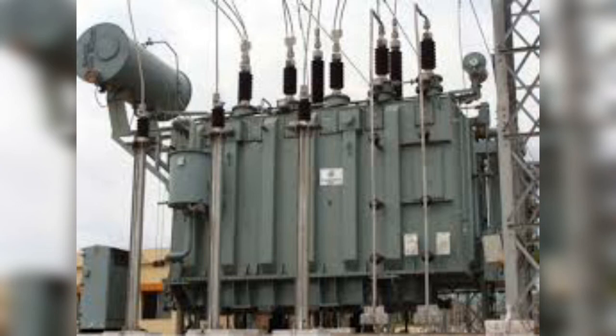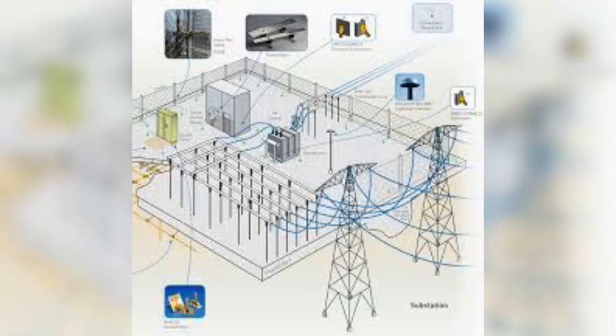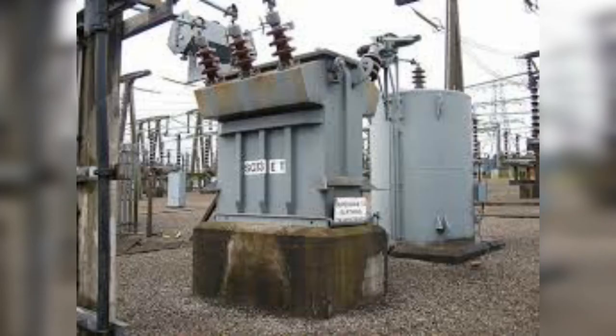Although a substation's grounding resistance is not in itself a guarantee of safety, there is no simple relation between the resistance of the grounding system as a whole and the maximum shock current to which a person might be exposed. A proper grounding level for a substation is required. If the grounding is above 1 ohm, it is not proper. Below 1 ohm, the grounding is proper. Check the resistance.